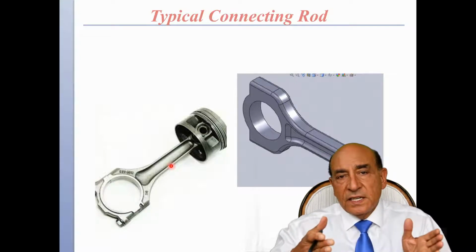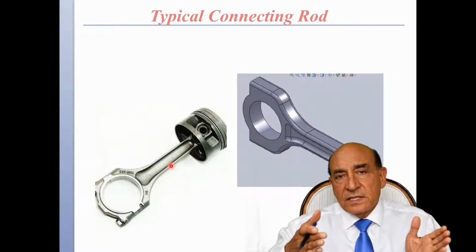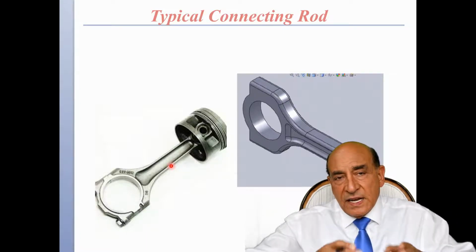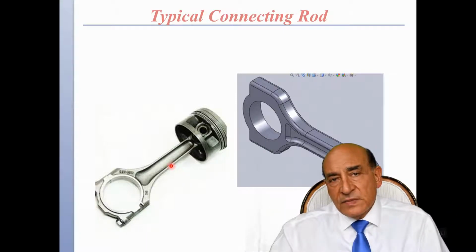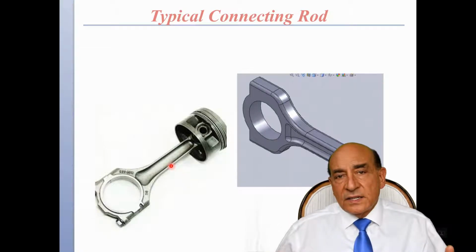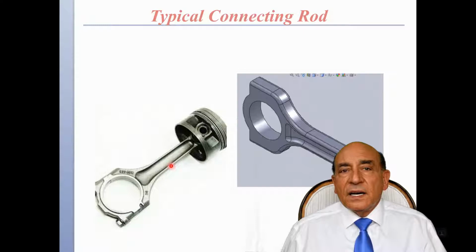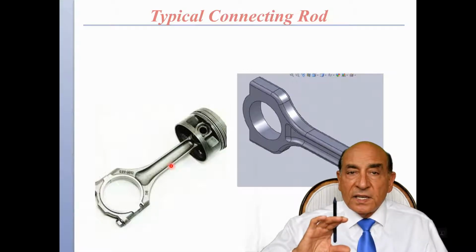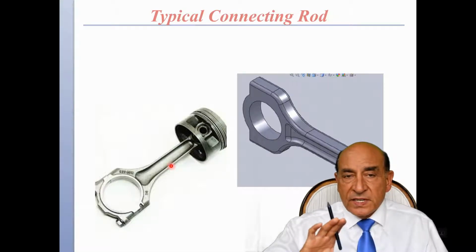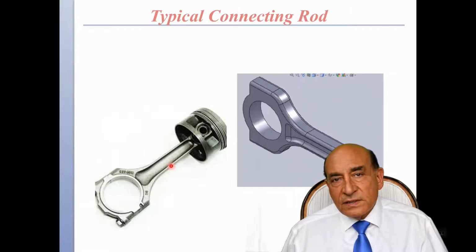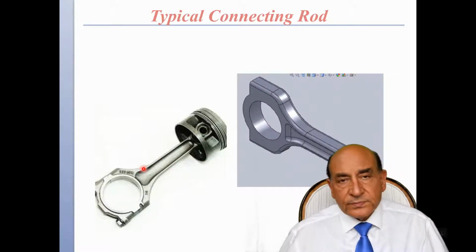You don't need to have a lot of volume everywhere in the I-beam, so you just cut out the middle part of the I-beam, because the moment of inertia that resists bending is proportional to the depth cubed, and therefore the depth is very important. The width is not that important, so you can cut it back in the middle. And that's what happens here.